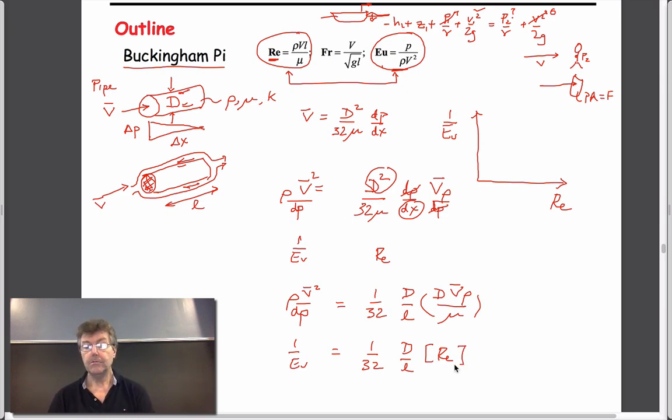And so now we have a unique relationship between these. It happens to be for laminar flow within a pipe, so one where we don't get turbulent behavior going. And so if we plotted that, I guess as Reynolds number increases, Euler number will decrease, so we get a curve like this, right? It has to be some curve. So this would be this relationship, this boxed relationship.